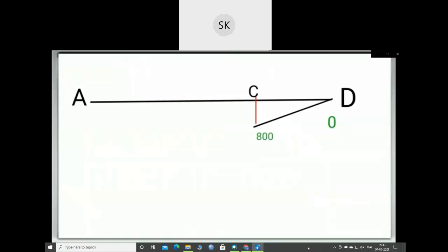Now the bending moment calculated at point B is equal to minus 2000 Newton meter. So we will mark this point as 2000 Newton meter to some scale below the baseline, and join these 2 points by a straight line, since this span BC follows a straight line rule. The bending moment calculated at point A is equal to minus 2700 Newton meter.